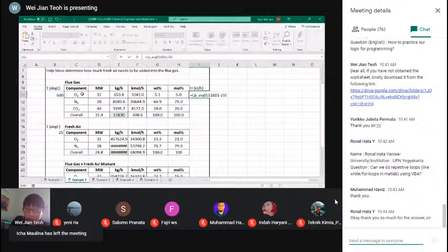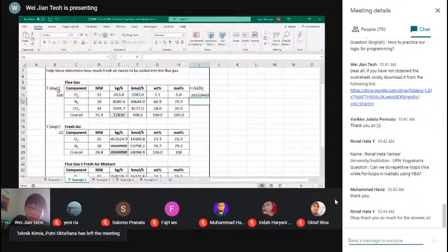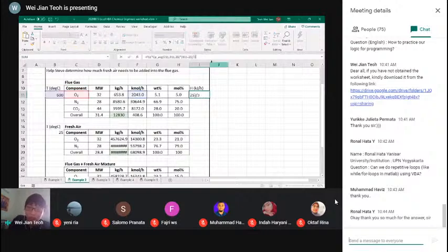And for the gas, I'm going to show this like this. I'm going to calculate the CP average using a temperature of 625. I'm just going to assume this is the correct answer. In real life, you might not be using this formula, but just for a simple example. After I get the CP, I multiply by the kilomole per hour, okay? And I multiply by the temperature difference, T minus 25. In this case, this temperature is 600 minus 25. So I get a very big number because this unit is very small. This is a kilojoule per hour. So let me just show the unit in kilowatt. So I divide by 3,600.